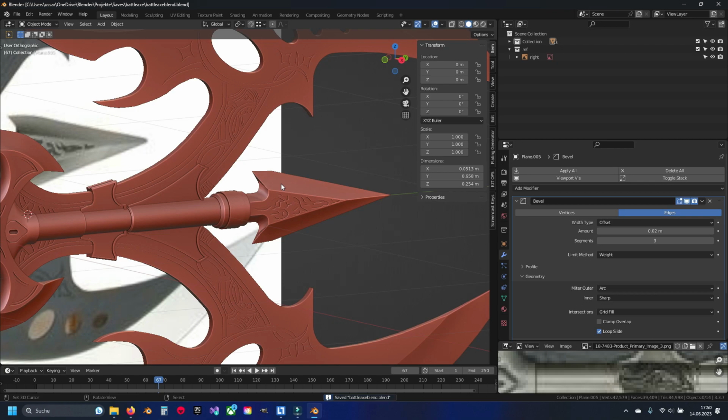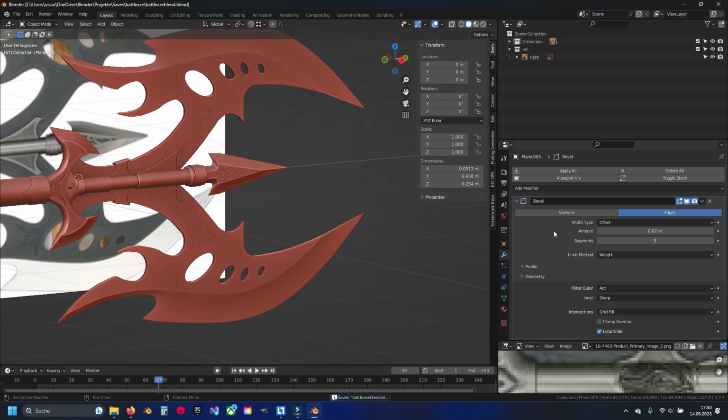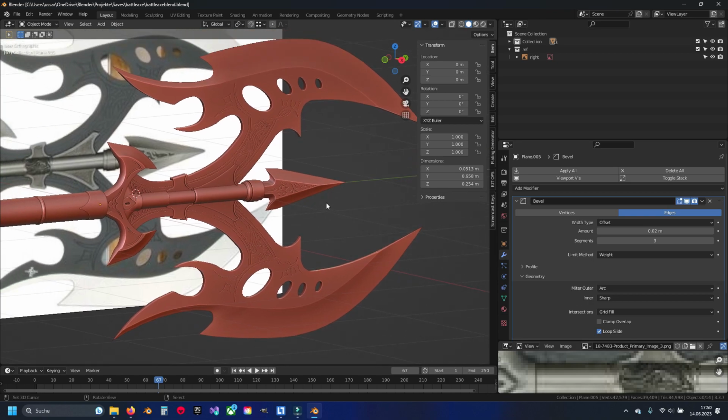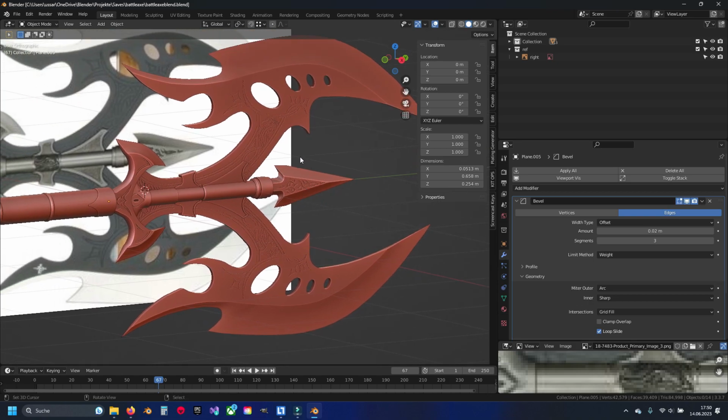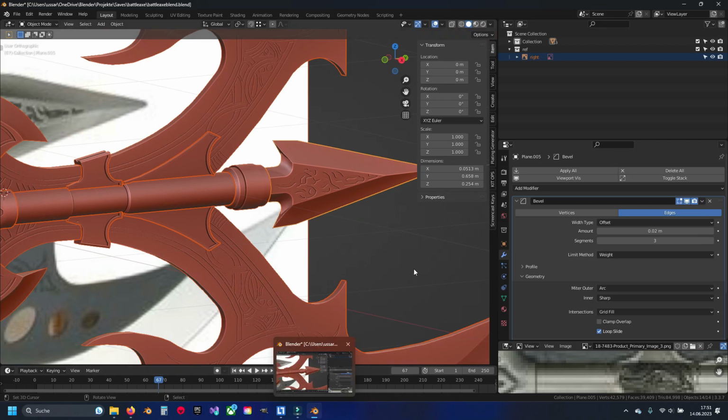To avoid having to activate this bevel modifier on all of your objects and do the settings manually, you can select all, with the active object being the one that has the bevel modifier on it, and then go to this little arrow, Copy to Selected. But I see we have a little problem down here.